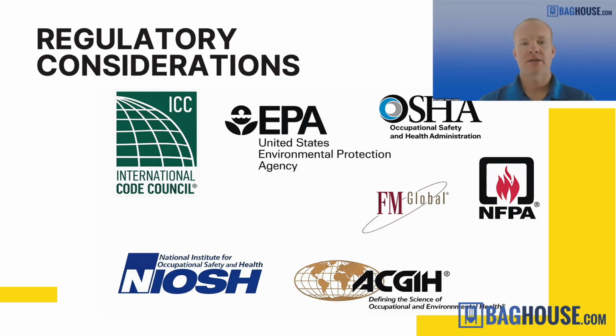Regulatory considerations. So if you're operating a business in the United States, of course, you are subject to OSHA. They have a general duty clause, which basically says that you have to make sure that your shop is safe for your workers to be in. And relevant to a wood shop, of course, that has to do with dusty atmosphere and combustible dust.